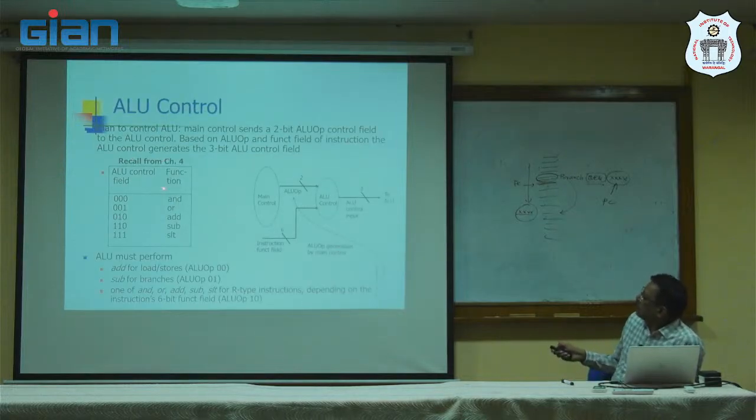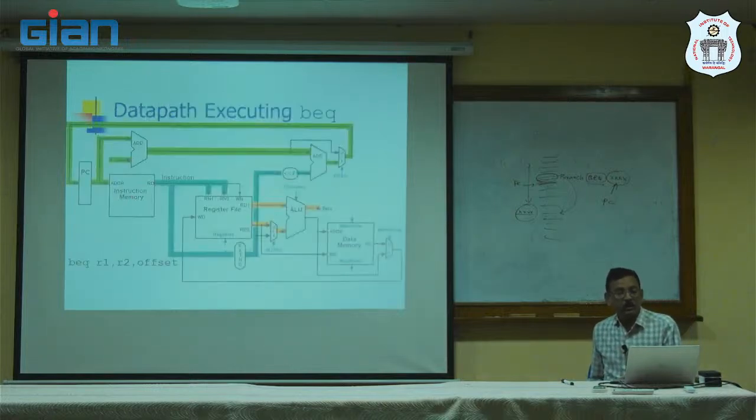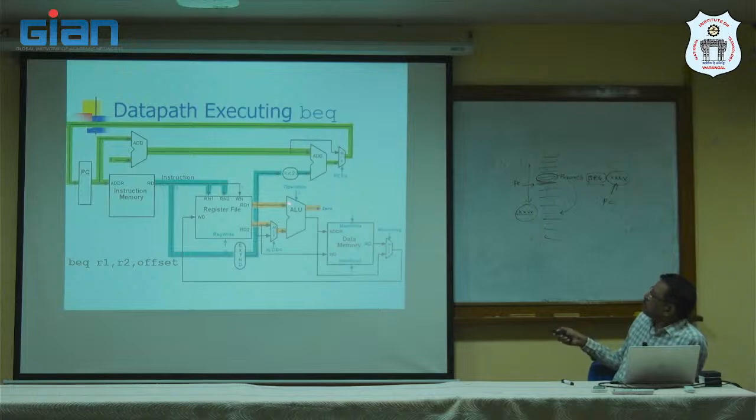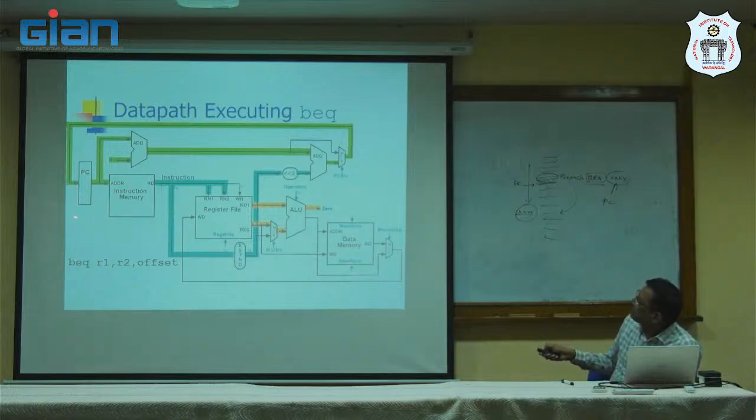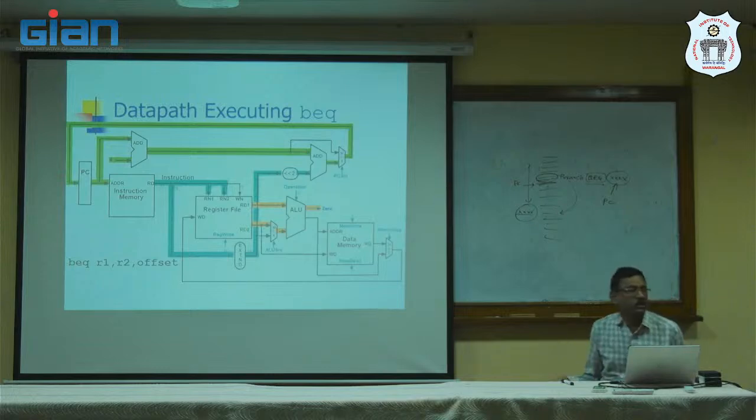The controller, because here what are the control signals? If you see, these are all control signals. Here source selection, the operation, because three control pins are there. So this will select 8 different operations of the ALU: addition, subtraction, OR operation, AND operation, shift operation, load operation, store operation. This will be selected by these 3 bits. And this is source selection, the multiplexer, whether you have to take this input or this input. Again one more selection here. And memory write, memory read, and register write. Register write, ALU source, operation, PC source, memory to register, memory write, memory read. These are all control signals.